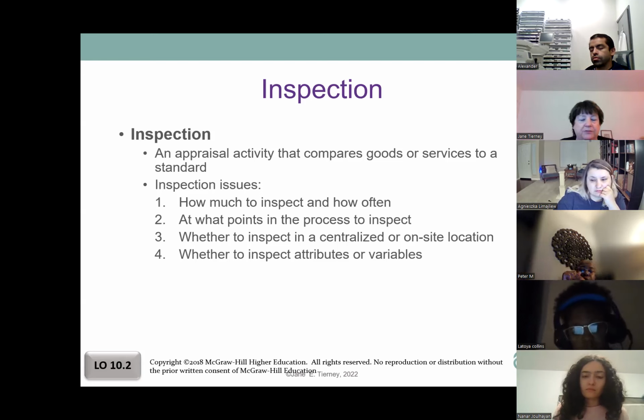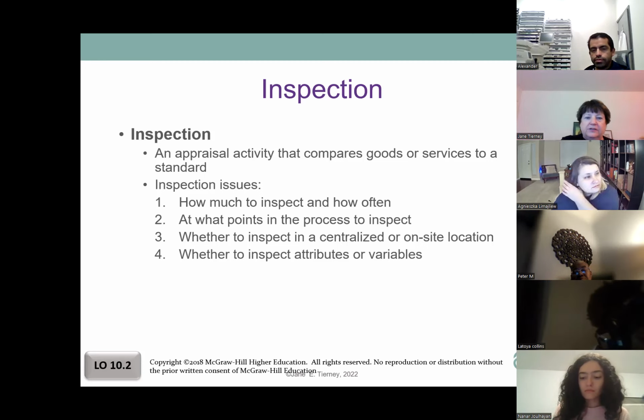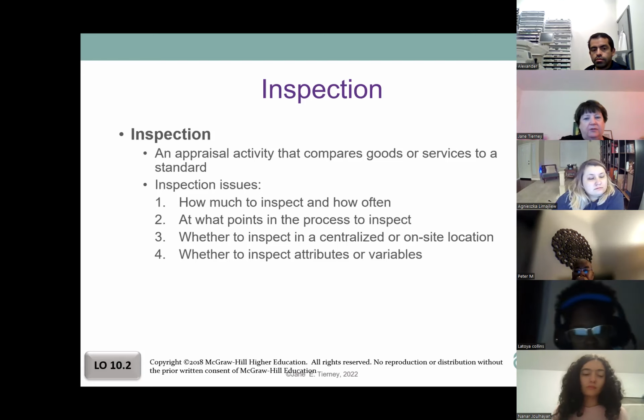If it's an attribute data, then it's going to be how smooth is that floor. So there's a couple components if we want that nice smooth finish. One is how level it is, but the other is just how smooth it is. So we might have a little leeway in how level it is, as long as it's smooth and it's not detectable that it's going up and down and up and down and up and down, right?